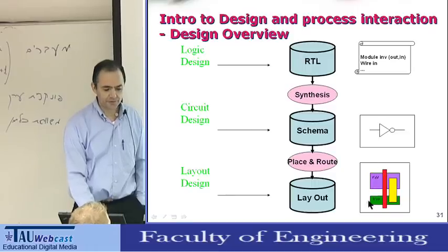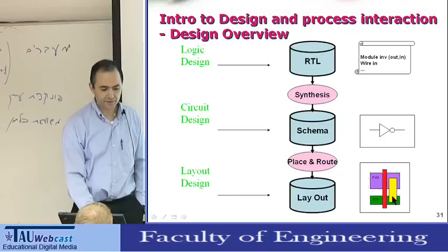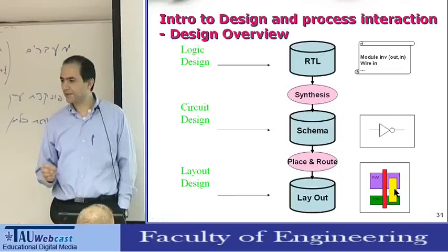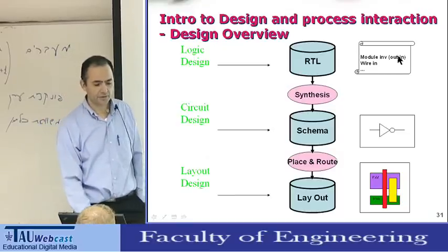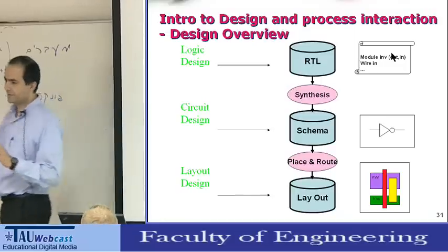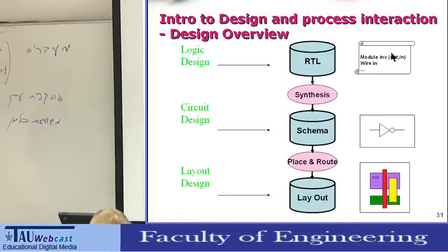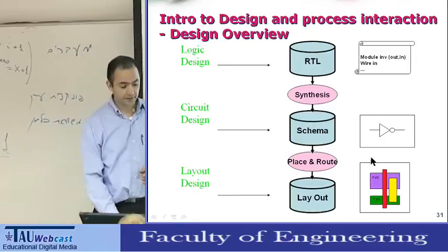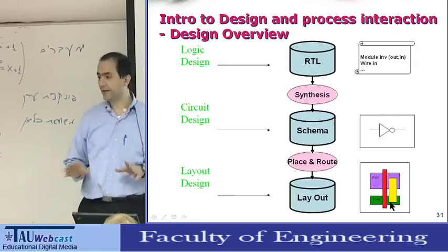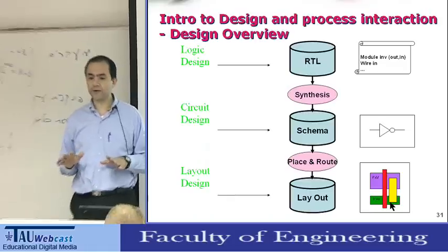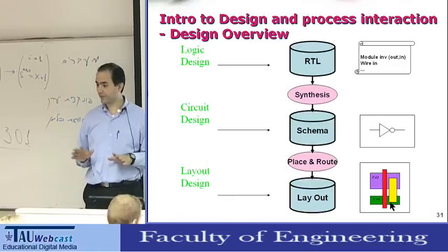So what I want to focus on is this area where the different colors are different layers in the process. So what we do is we take, for example, if we want to take a processor, the processor is made of certain parts, and those parts are translated into more basic parts like NAND gates, NOR gates, and so on. And then those are translated into layout, which, where is the layout? How does the layout get into the wafer? Through what? Through lithography, through the mask.